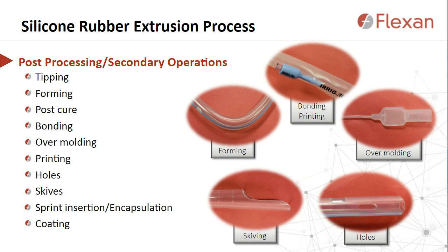As some of you may know, silicone can be molded over substrates such as metal and some plastics. When dealing with extrusions, a molded feature such as a hub can be added to make it easier to access the lumens. The hub may also be the intersection of multiple individual access points, as seen on many catheters. This process may also require special primers or substrate preparation methods.